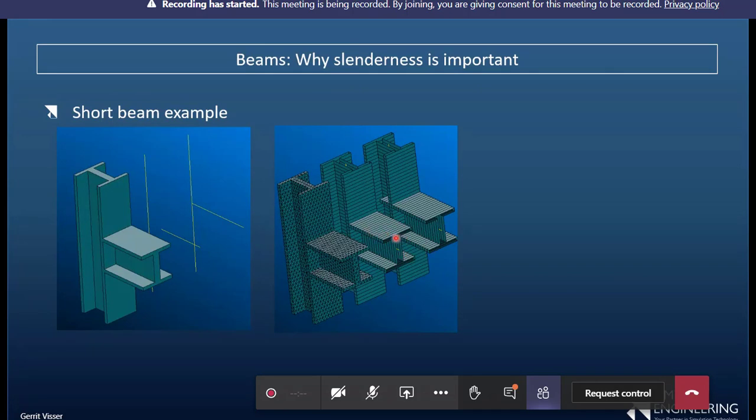But it also sounds worrying, because if I look at that section, that beam element is much shorter than that section length. To give you an idea, the beam element was 2 millimeters long, but that height is 20 millimeters. Is that an issue? Is that an aspect ratio issue? No, it's not. The aspect ratio refers to the beam as a whole, not locally what the element looks like. I've seen lots of examples where people try and argue that it's about the element size. For shells, the equivalent would be when the element itself is smaller than the thickness, it doesn't make sense, and that's not true.